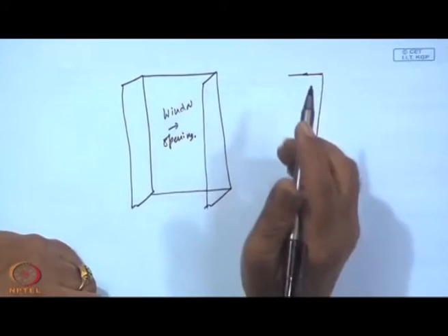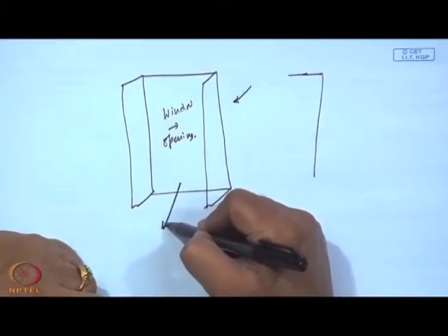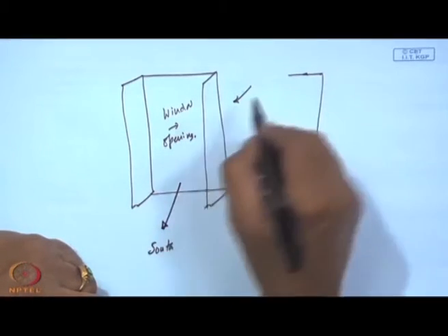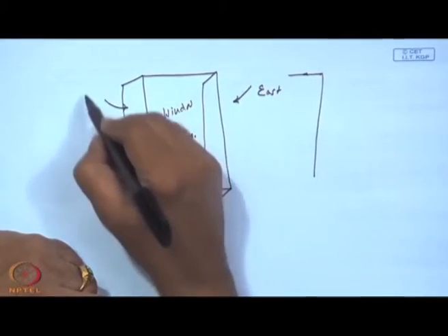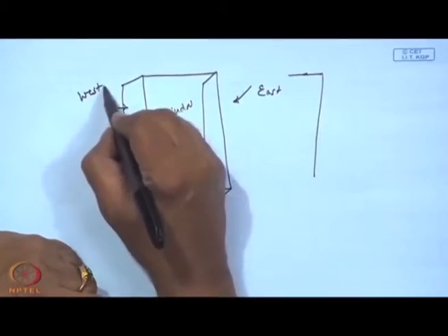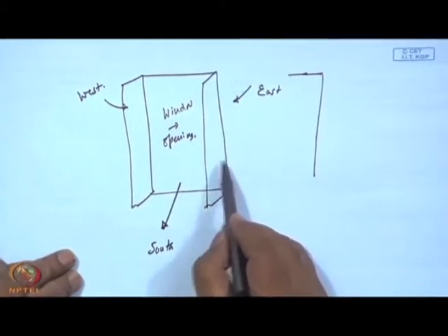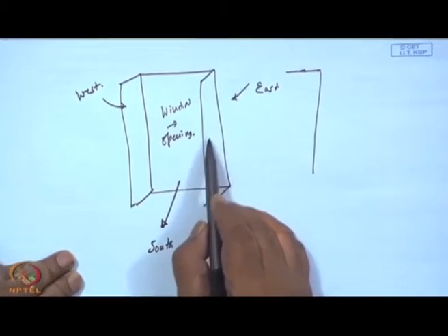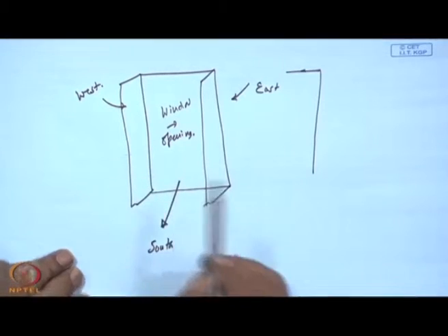These are on the sides, so that if this is south and if this is east and this is west, these wing walls will prevent sun's rays entering the window or the opening in the morning time from this wing wall, and in the afternoon by this wing wall.